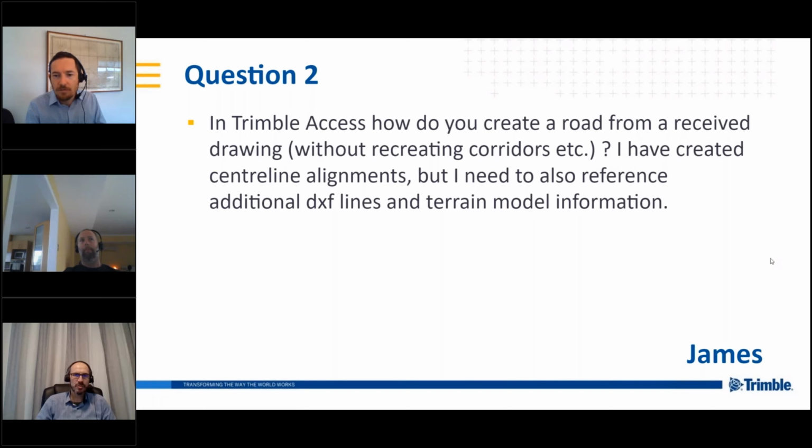If you did want to use a string-based road format with Trimble Access roads, the formats supported are the GENIO or GNIO format, and also new to Trimble Access 2020 is a LandXML format, where you can have your master alignment, then you can have break lines for your substrings. That can be exported from TBC.